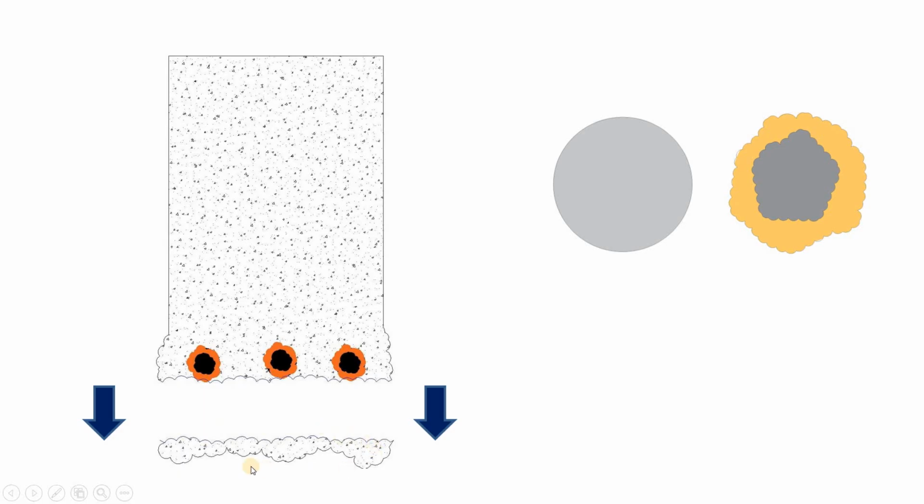When the concrete is spalling like this, it is not a very small material. It is of 10 or 15 kgs of weight. When it is falling from a height of 3 meters, it is enough to kill a person. So an engineer must be very careful in giving the provision for cover. The cover only gives the reinforcement protection from rusting.